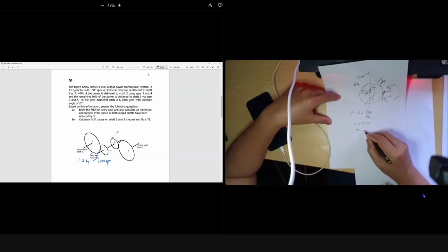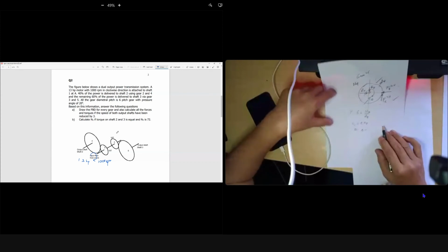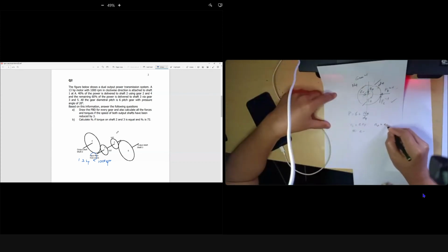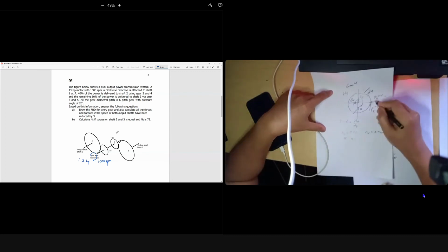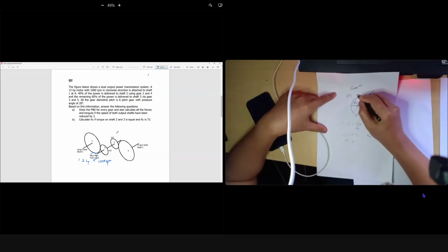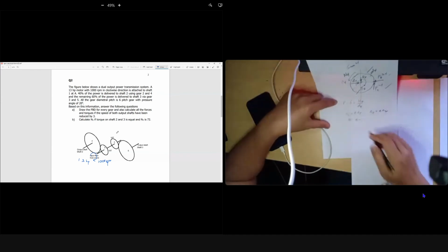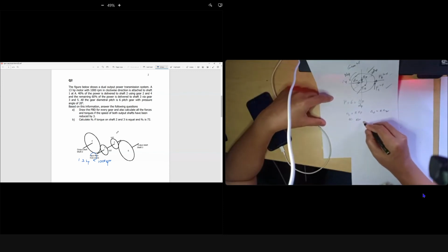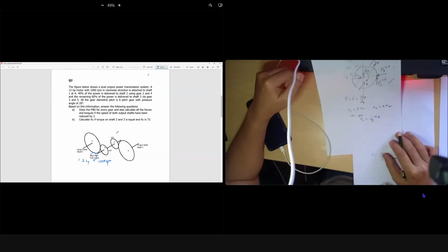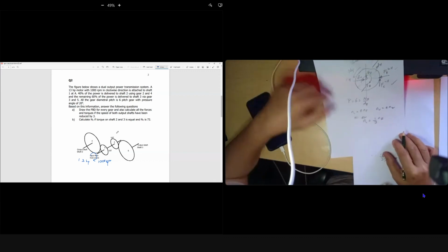Okay, just see what our formula is. N last, you mean your N4. N4 relates to N2 because the driving gear is 2. It is turning clockwise like this, so N4 turns counterclockwise. This will be your N4. So what is N4? N4 is reduced by 3, right? So it means N last is 1 over 3 of N first, right?